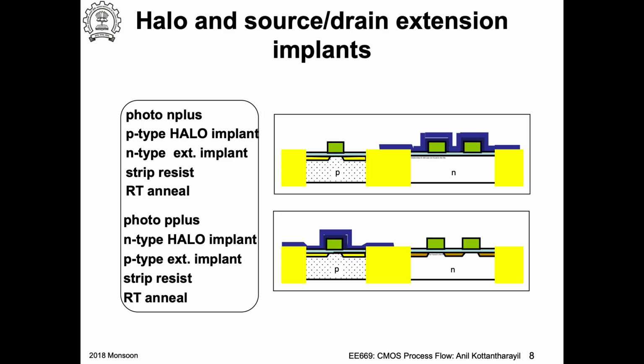Okay, so 2 quadrants, if you remember. This will be from a tilt from the vertical towards the left first. Okay, and then you are doing a boron implant. So some of this boron would actually go under the gate, at the left hand side edge.